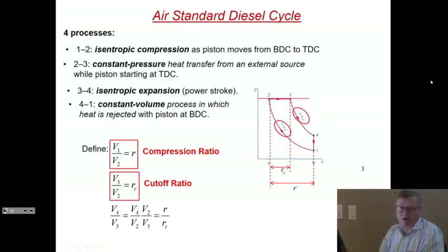Now we are going to make an air standard diesel cycle analysis. So we have 1 to 2 isentropic compression, classic isentropic compression here. 2 to 3, this famous new constant pressure heat transfer, constant pressure combustion from 2 to 3. So in a PV diagram, this is a horizontal line from top dead center to some way down in the volume change.